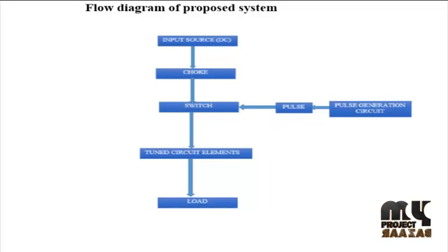The next one is the coil. Coil is also called an inductor and is another primary type of physical component that is used in electronic circuits. It has two leads and is typically implemented as one or more windings of conductive wire. That wire is often, but not necessarily, formed around a core of iron or steel or some other magnetic material. When current flows through the coil, it induces a magnetic field that serves as a store of energy. Generally, inductance is measured in henries.